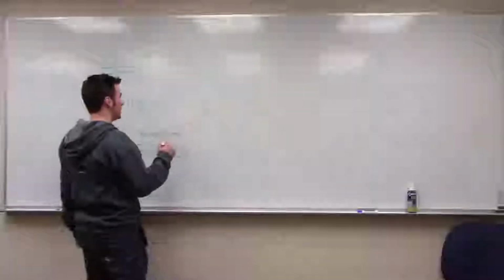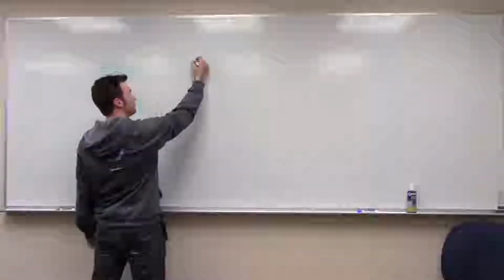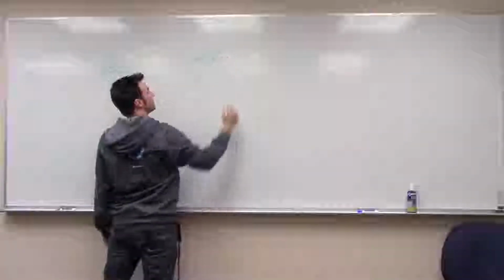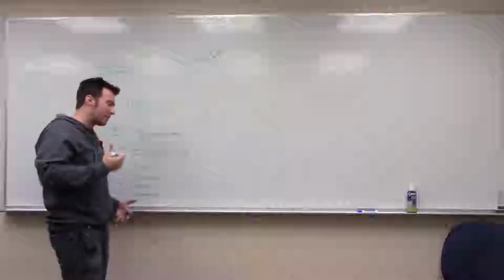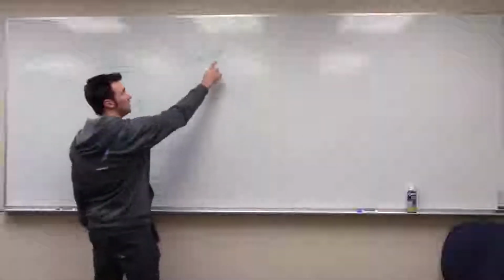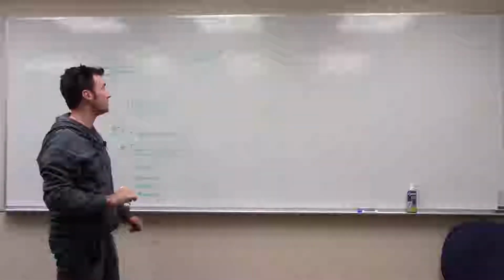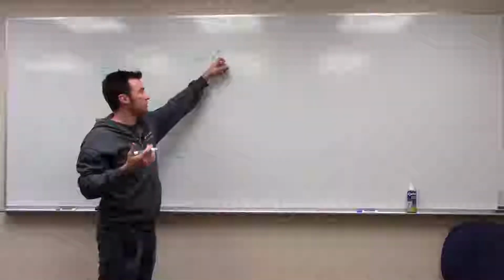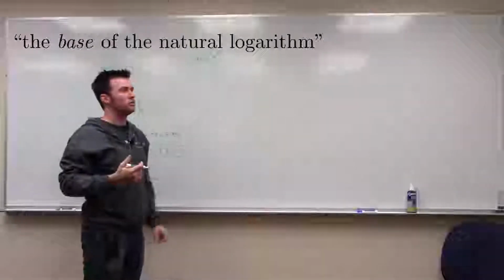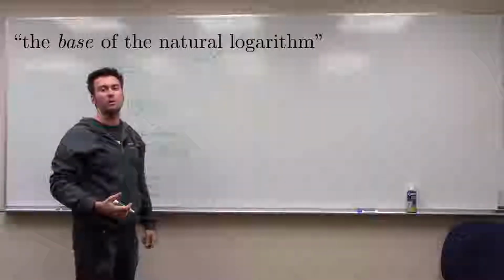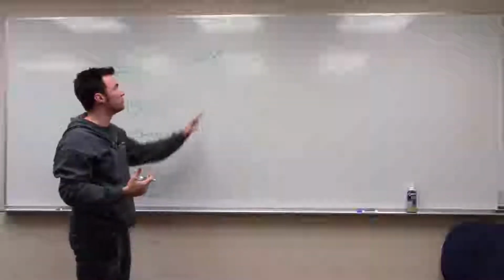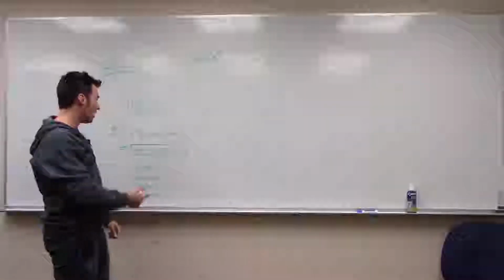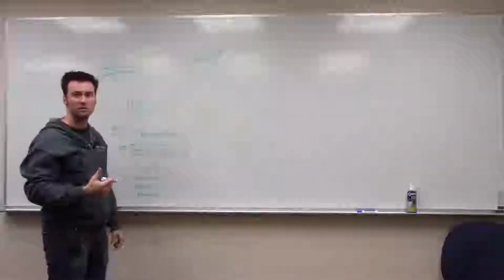So we're going to guess, in this case, a solution x of time is some function e to the rt. We're going to guess that that's the right form. t is just time, e is Euler's constant, the exponential e, the base of the natural logarithm, and r is some variable that we haven't determined yet. We imagine that there is some constant for which this will be a solution, but we don't know what the value of r is. It turns out we're going to see that r is going to depend on our quantities m, c, and k somehow in our equation.